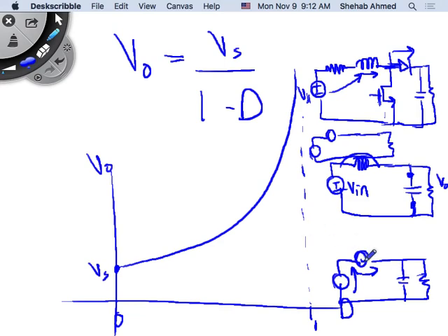So this is increasing the output voltage across my load, meaning it's increasing my average current through my load. My average current through the load is also the average current here through my inductor, because the capacitor is an open circuit for DC, right? So which means that if I keep increasing my duty ratio, I keep increasing my average inductor current.